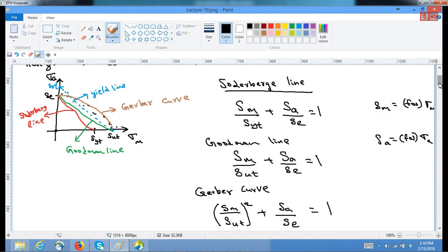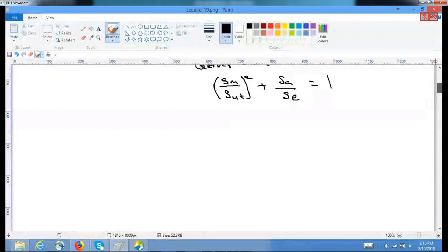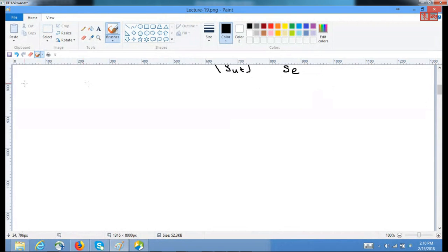These are the kinds of things we generally follow when fluctuating stresses are there. Then we have also corrected the Goodman curve further, because at higher mean stresses only yielding would take place, and hence we have proposed a modified Goodman line.